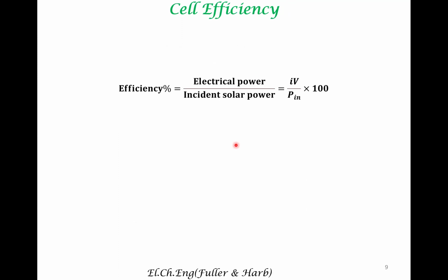So we can also talk about electrical efficiencies, right? What is incident solar power? It's about 1 kilowatt per meter squared on, let's say, a hot sunny day, the middle of the afternoon. This is called solar insolation. So this again varies from place to place depending upon the latitude and longitude of the place and the time of the day, right? Even if you consider solar energy conversion, probably you can utilize the device for about 6 hours a day. That is another disadvantage, right?